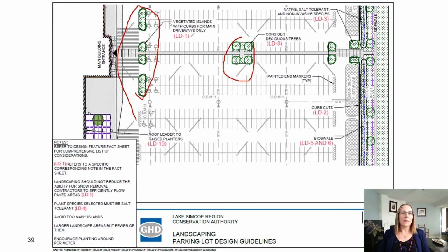The inlet of a bioswale should be designed to promote sheet flow in order to limit erosion and also to maximize contaminant removal. So you can use your landscaping features to actually improve the water quality. But there is pre-treatment recommended before the water goes into the bioswales. And then finally, the vegetation in your bioswales, if you're using them, should be both flood and drought tolerant, as they'll likely be exposed to both situations. So plants with deep roots.